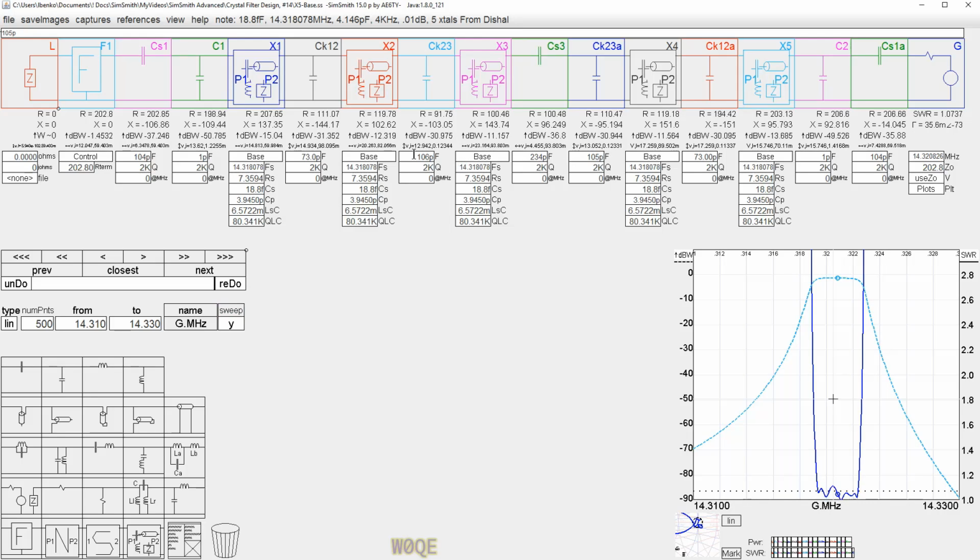It's really hard to say whether these changes are so small that they're hardly worthwhile. So for the most part, unless you're really doing something critical, the capacitance that you get across the crystal, trying to attribute part of it as a capacitance to ground, makes much less effect than a lot of other things you can do in the design. So if it was me, I might reduce these shunt capacitors by a picofarad or 2, but it's hard to argue that it has any real merit.